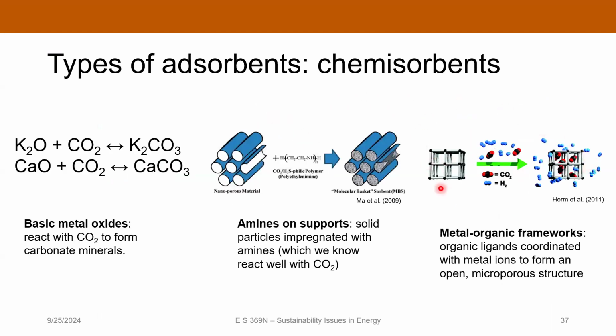But I mentioned that probably the most advances we're going to see in sorbents for direct air capture specifically are these metal organic frameworks, which are really cool molecules that can be engineered to give you preferential sorption behavior of certain molecules. This is a really big problem with these sorbents, that you get these competitive effects.